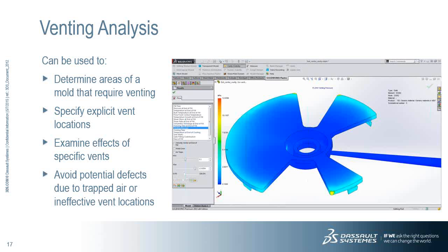And also then we used to see where all the inserts were required. We used to make a cut of that in the CAD tool, and then make an electrode, and then spark it, and then insert it in the core or cavity. So this was a long process, and it was time consuming, and these things used not to be included in my PERTs or Gantt chart where the production planning or the process planning is done. So it used to take a lot of time, and we used to deviate from the schedules most of the times. So these kinds of problems can be avoided when we have such features or such tools in place.